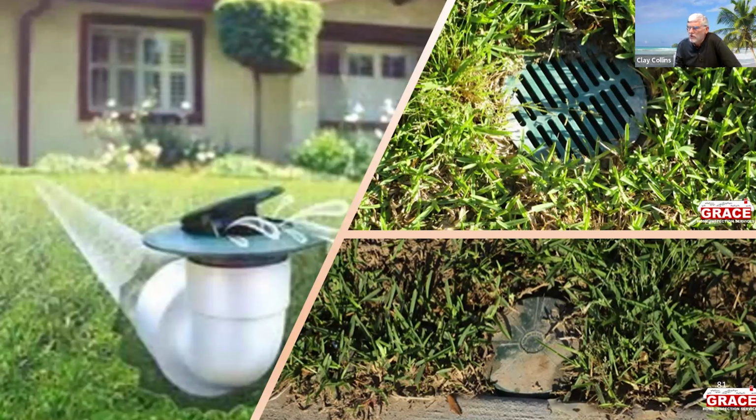Another thing to watch is when one home has a lawn irrigation system and another doesn't. Not quite sure what you mean, but the one with yard irrigation can impact yours if they don't have good drainage and they spray their water too often and it runs into your yard. That can impact it. If your drainage swale is proper, then the drainage swale stays wet rather than actually impacting your foundation.